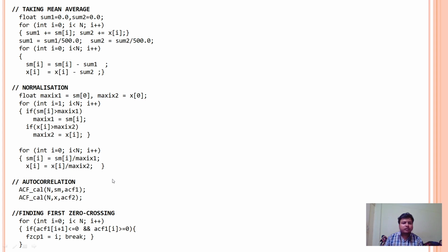Here, the AC function which I made is based on the same formula which we discussed earlier in the slides. Now, let's talk about the further methodology we need to calculate the period of the given PPG signal. Firstly, we need to calculate the first zero crossing point. As we talked about, autocorrelation measures the similarity of a signal. So basically, a zero crossing in the autocorrelation function states that there is no similarity in that function, implying similarity is zero.